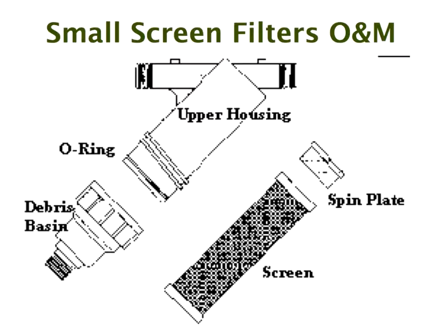Okay. This is one of the most common filters you'll find in single-family homes, which is a screen, which is inserted in here. We recommend either a solenoid valve here, which can get opened at every cycle, or alternatively, you can have a normal ball valve and just crack it open a fraction so that when our system's operating, it is continuously flushing through the center.